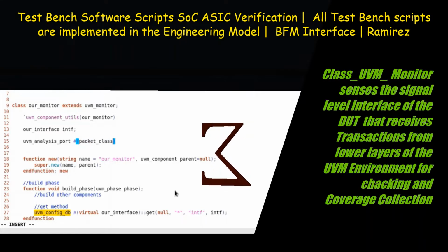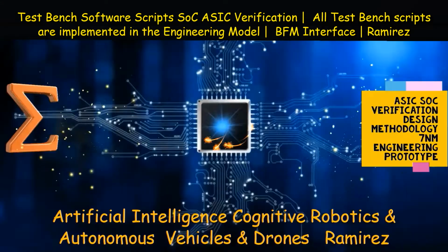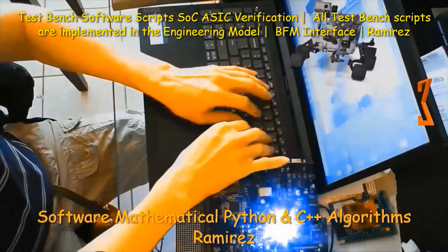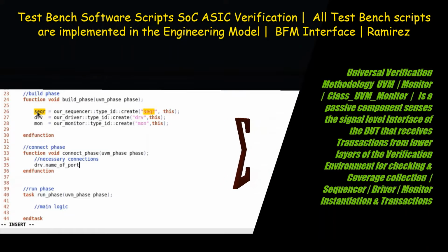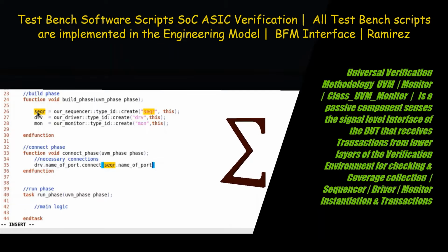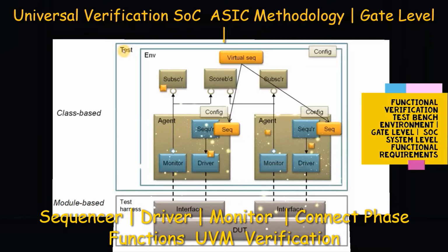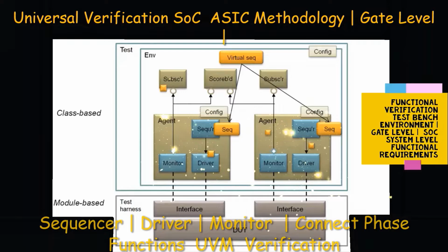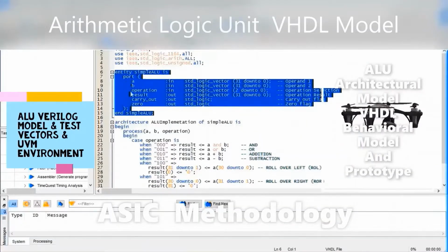is that the virtual interface within the top level configuration object is set to point to the BFM interface within the test harness, that is top_hdl_th.bus_bfm_0. This is a full hierarchical reference to the interface instance of bus_bfm_0 within the top level module.